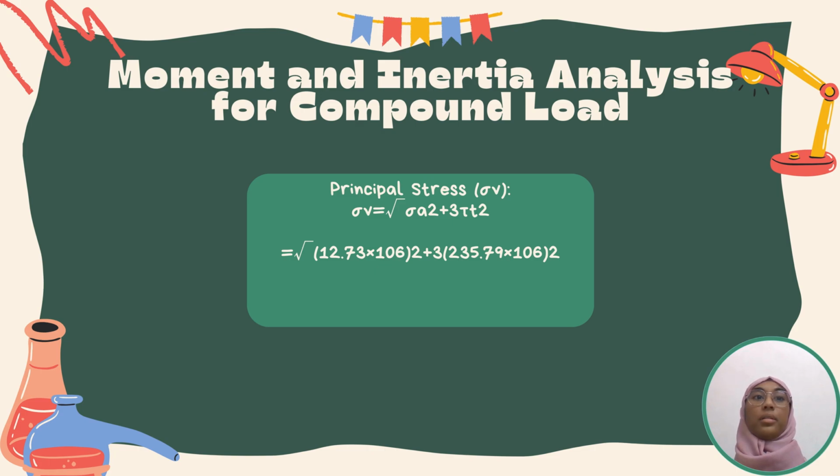Third is moment and inertia analysis for compound loads. We analyze compound loading conditions using the principal stress formula shown on the screen, and the result is 408.59 megapascals. This analysis helps us pinpoint critical stress areas in the staple mechanism, allowing for targeted design improvements.